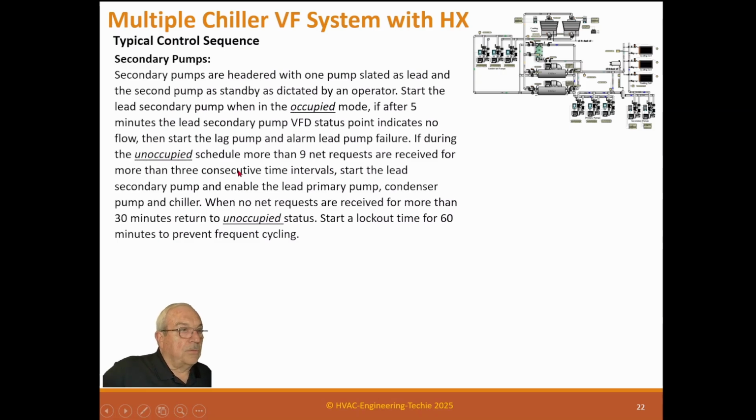Okay, typical control sequence, secondary pumps. These sequences get somewhat lengthy. Secondary pumps are headered with one pump stated as lead and the second pump as standby as dictated by an operator. Start the lead secondary pump when in the occupied mode. If after 5 minutes the lead secondary pump VFD status point indicates no flow, then start the lag pump and alarm the lead pump failure.